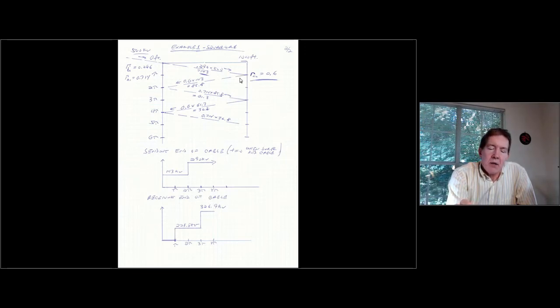When I see this reflection coming back, this 85.8 kV waveform, it's going to see a reflection coefficient of 0.714. So 0.714 times the 85.8 gives me 61.3 reflected back toward the load. Take that, multiply by 0.6, it goes back toward the left, has another reflection coefficient, and it's going to go back to the right.